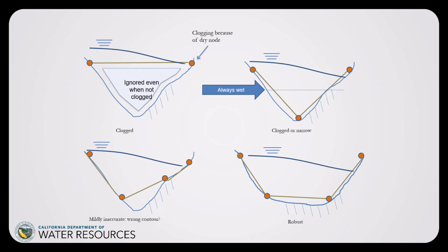Okay, so let's look at some cases and possible pathologies. In the top left case, we have gridded only at the shores, at the two red dots. Our preprocessor will adjust this a little bit, but if you gave it to SCHISM just as is, then what would happen is it would just see shallow on the left and shallow on the right, and it wouldn't even notice that there's a channel in between the two. So you'd have no conveyance in that channel.